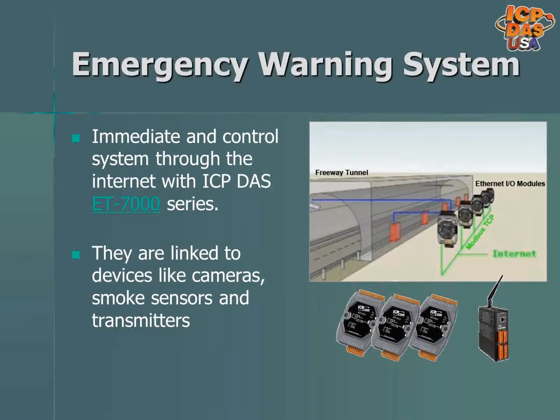Cellular controllers like G4500 operate over the 2G and 3G cellular networks and support Modbus protocols. They can be programmed in C language and allow for sending of text messages and emails based on information from data acquisition equipment.